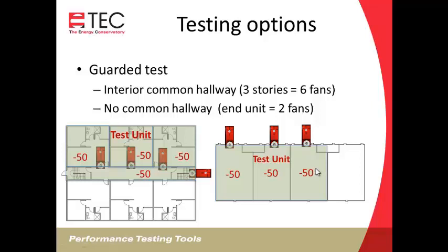You do certainly, if you've got a crawl space or an attic, there's going to be air leakage through those spaces, and this space will be depressurized somewhat, and the value of your test unit may be different if you have the 4th one depressurized also. So that kind of gets into what a fully guarded test is compared to what a guarded test would be.